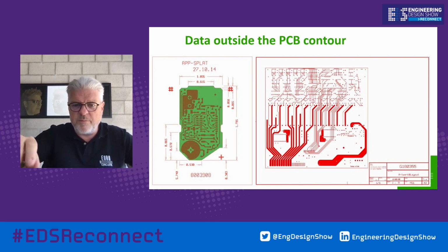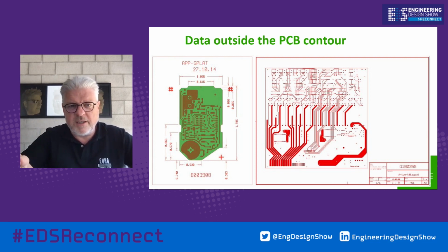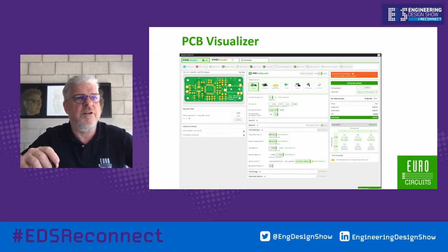Also, avoid information outside the PCB data contour. There is no point in putting all these frames around your data or putting measures in how big your data is. The computer is much smarter than the operator behind it and can read this perfectly without all this cluttering information.